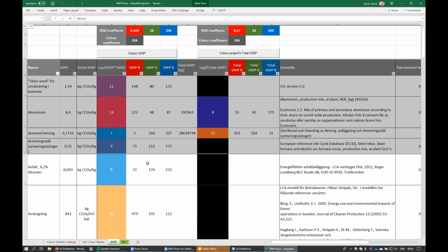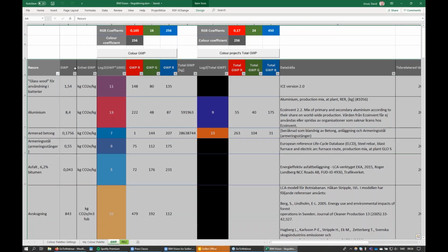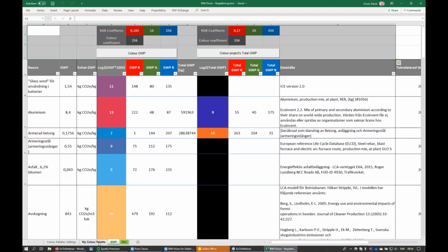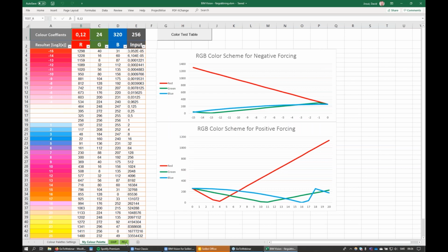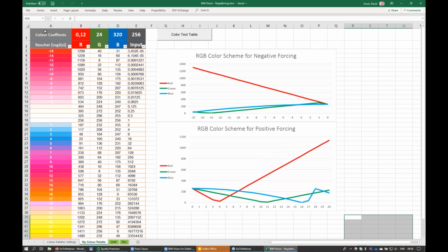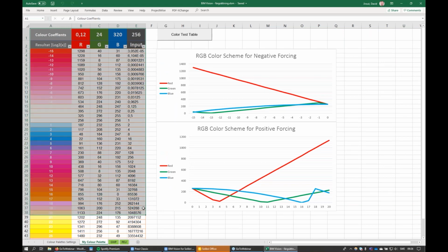This part of the Excel is a database, whereas this part is a mesh of values. Sometimes you get Excel data and you've got parts of data here, parts of data there. This is not an Excel database. For an Excel database, you really have to have one integrated table. And this is what you can import in Solibri.